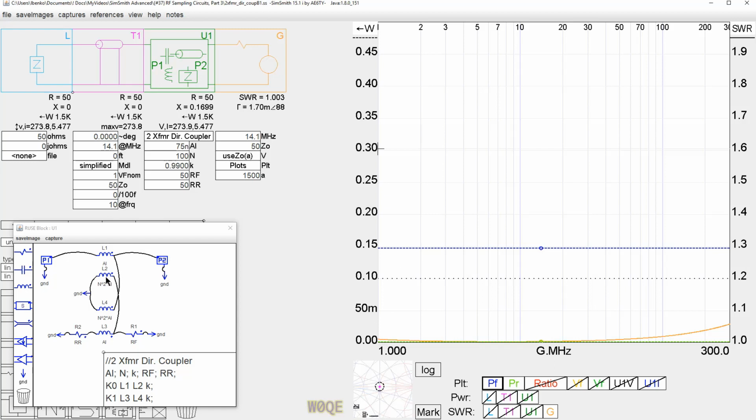However, this circuit cannot be built very nicely. This circuit is shown as being very simple, but in reality, 100 turns on an inductor here is going to have a resonant frequency. It's going to be quite low, down probably in the 5 megahertz range or so, or even lower. And there's stray capacitances. The stray capacitances we saw before and how they affected the current sampler will affect this circuit also. I am not including them in this